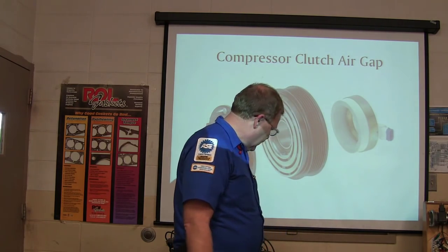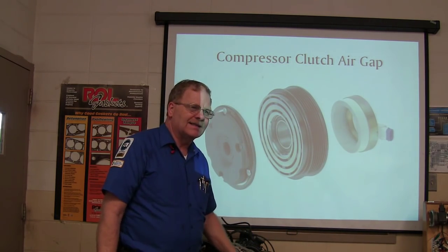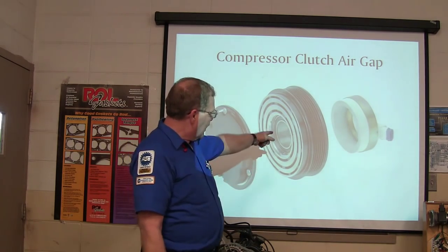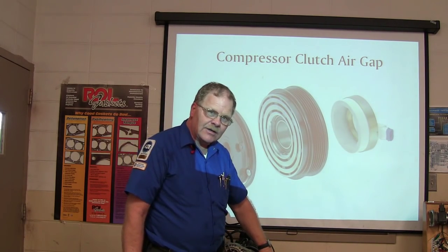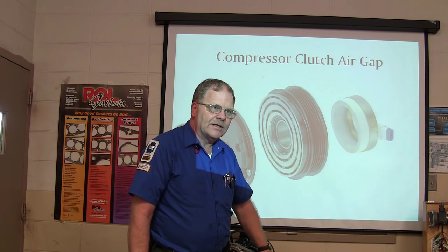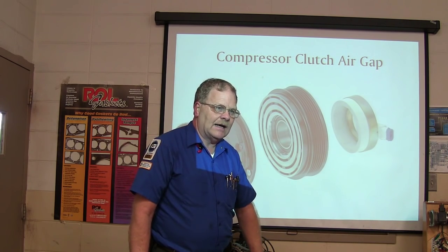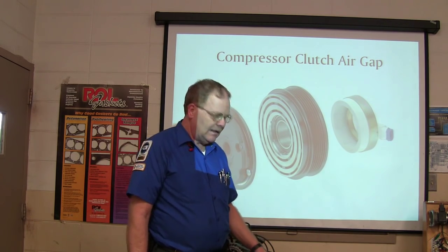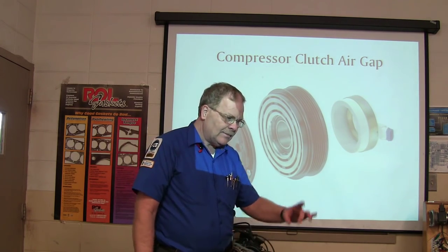You basically, it's got to have a lot of power. It doesn't need a lot of speed, but it needs a lot of power and a lot of belt traction. So the air conditioner and this have both got big pulleys on them, because it's hard to pull those things. So you put a bigger pulley, it can handle it. If you put a little bitty pulley on your power steering, it'd slip. You know what I mean? Like if you were to doctor one and put a little bitty pulley on.